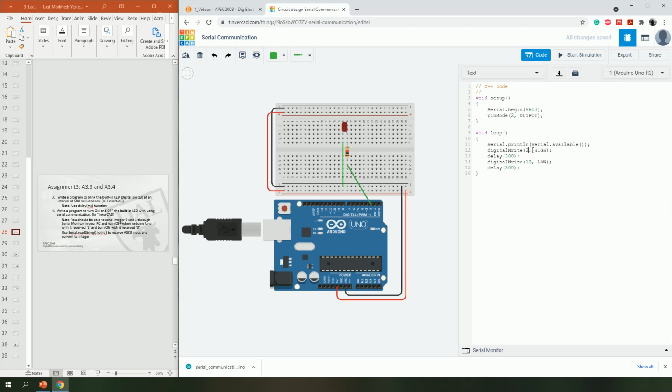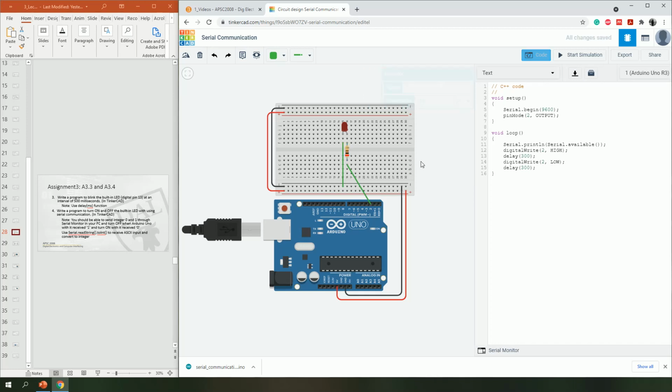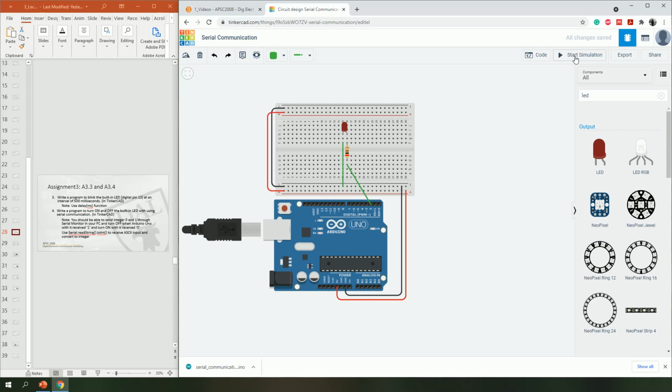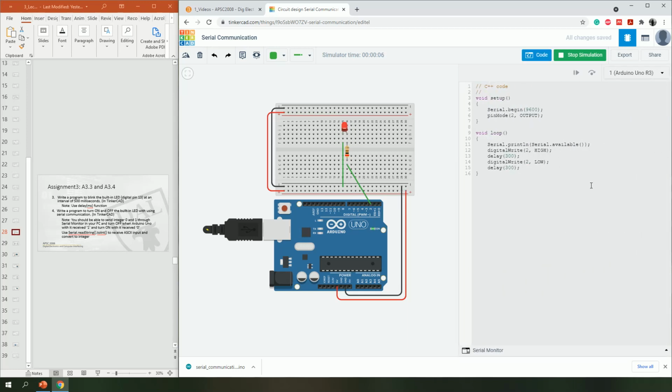And I'm going to set pin 2 as HIGH, and for the resistor I would say some value between 200 and 400 should be sufficient. So let me say 200. And let's get started. So it blinks at 300 milliseconds. So stop. Maybe let's do 2 seconds.